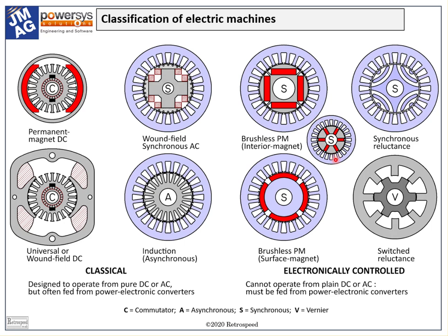Tucked in here is another embodiment of the IPM, the so-called spoke motor, in which the magnets are magnetized not radially but circumferentially. This again has its own characteristics, and it has been used in commercial products where lower grade magnet materials can be used.